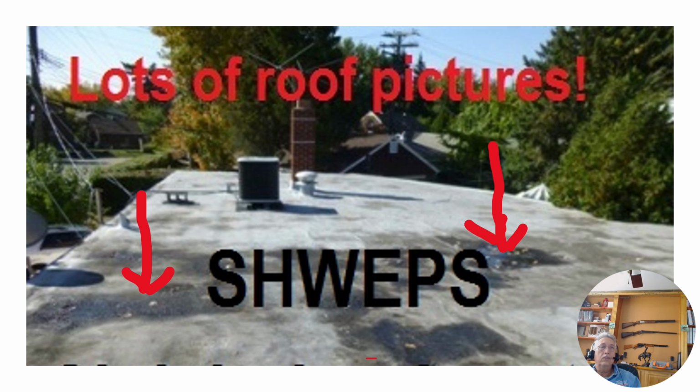Speaking of roofs, let's go on this roof. So this is why I picked this building. It had a pitched roof in the front. It's not that big, and it's got a flat roof on the back. So you can see this flat roof is kind of in tough shape with this long shot. We can see some sinkholes, and they're dark, meaning there's organic material in there because water's there a lot of the time, sunken in. So we're going to walk the roof. Okay.